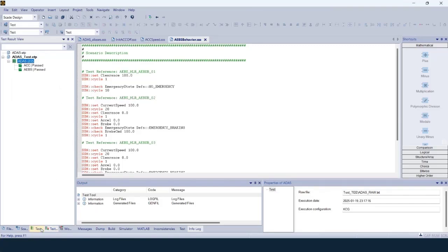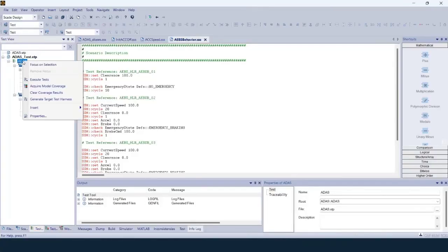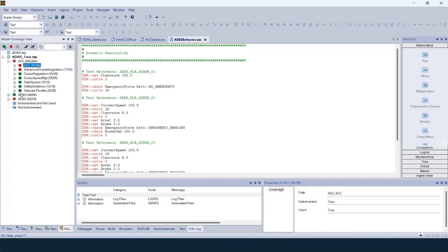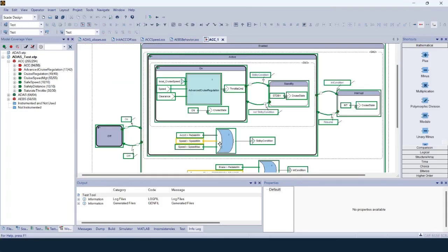of our project. Before wrapping up, let's talk about test coverage. By running the coverage tool, we can identify which parts of the system have been tested. Green areas indicate fully tested elements. Orange areas are partially tested, for example, if a Boolean was only tested for true but not for false. Red areas are not tested at all. While achieving 100% coverage is rare and often unnecessary, it's important to focus on the most critical parts of the system to ensure its safety and reliability.